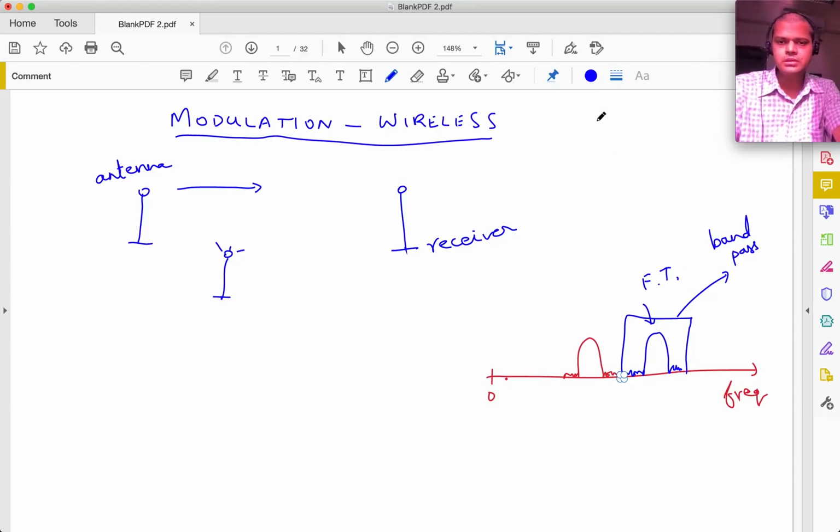So remember the terminology from the last class. A low pass filter is saying that I take all low frequencies up to a certain cutoff. A high pass filter removes all frequencies below a cutoff and lets through the high frequencies. Band pass is a combination of those. I take only a particular range of frequency, a particular band, out, and this is what is there in all your radios. So by ensuring that different signals, let's say from neighboring wireless transmitters, transmit at different frequencies, we can prevent them from interfering with each other.